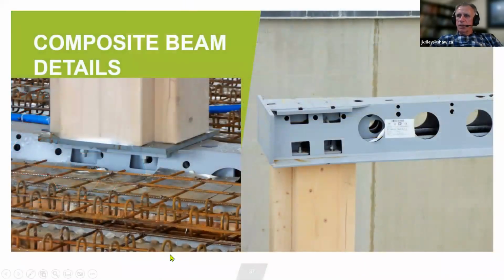Now, remember I mentioned earlier on the deck design. So here's a composite deck, TCC deck here. So you can see the beam. You can see how the column is fastened to the beam. Pretty simple construction, but very fast to erect. And there's a lot of tolerance built into that. So you can see here, what we're doing is beefing up that beam right there to carry the load of the building, because the load of the building goes right through the beam. But that has a limitation, and that's about 18 stories.